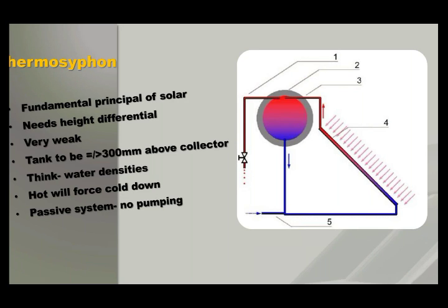If you were to have a thermosiphon system set up like that or close to that, let's say that the tank was level with the top of the panel, you could still experience reverse or slight amount of reverse thermosiphon, whereby some of the heat of the geyser actually gets radiated away by the panel. And that is not uncommon even in thermosiphon systems. So if you've got at least 300 mil between your panel and tank, you've negated that possibility.